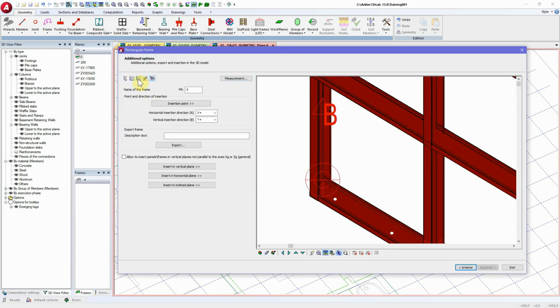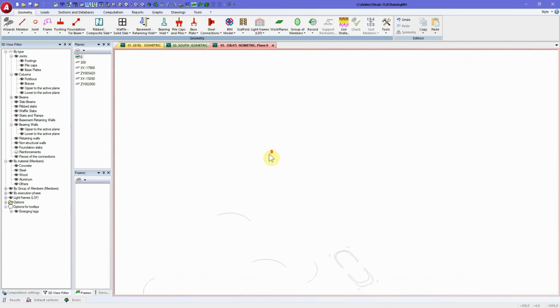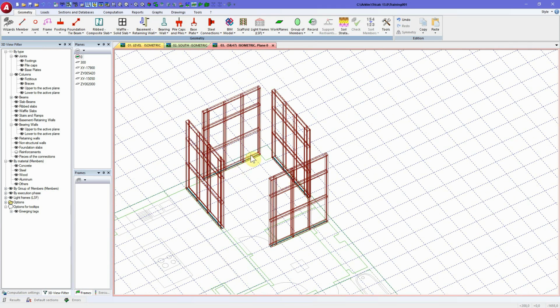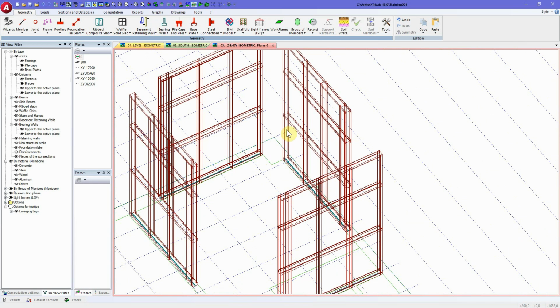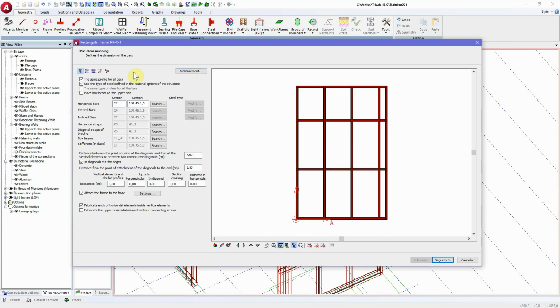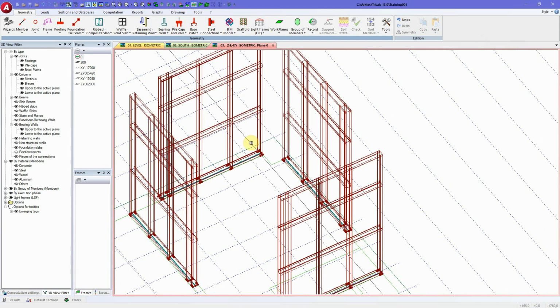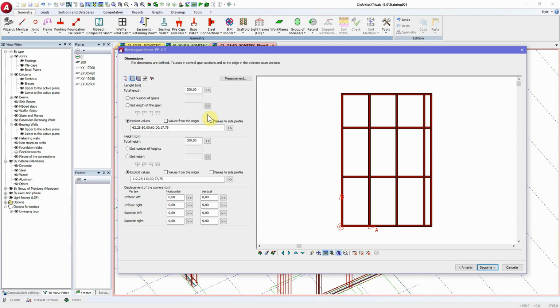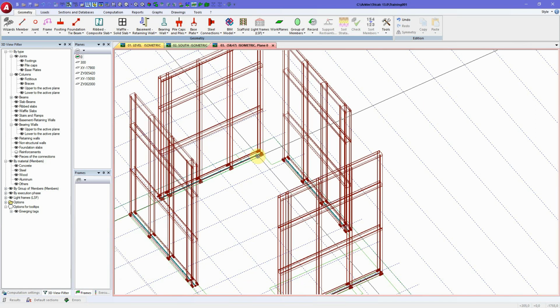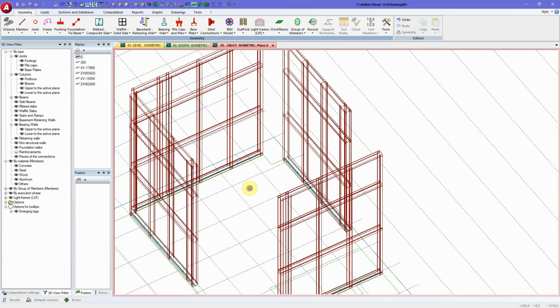As you can see, we have always used 2 meter length walls for an example. Of course, you could change the length of the panel to any other length that you'd like. So it is possible to modify the frame or even in the definition. When you select the length, you can select with this double arrow 2 points, and in that case it will select 1 and 2 points for reference, and it will measure the length that it will need. So it is a possibility to change or define the panel with another length that you like.